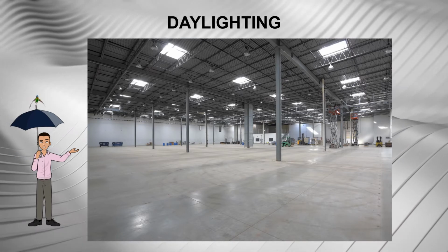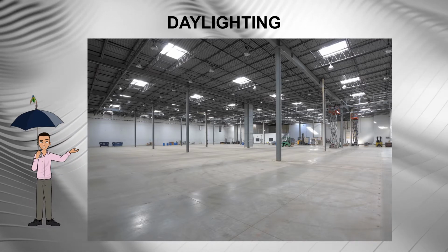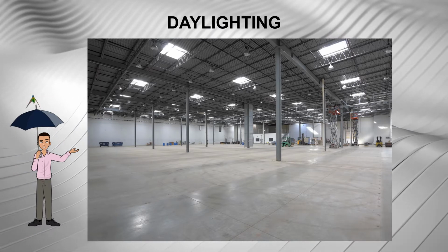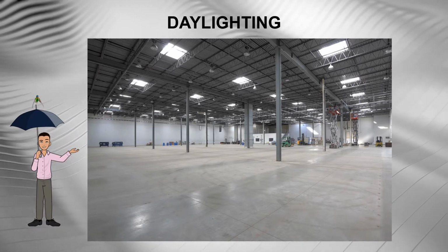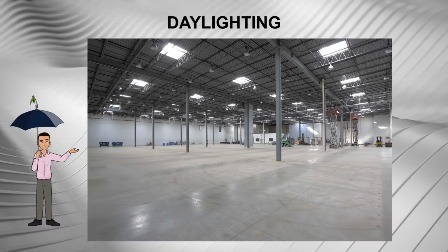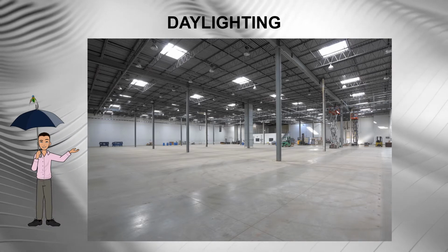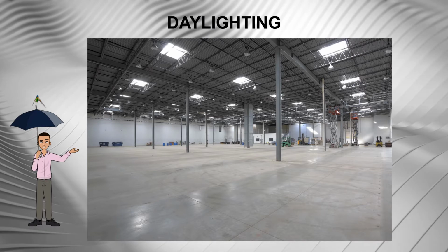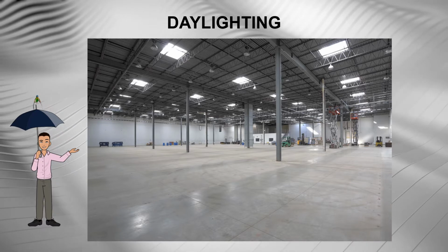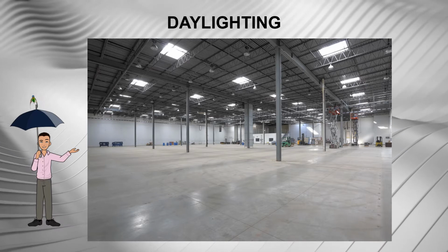Daylighting. Few industries now have particular needs in respect of daylighting, since shift work is often provided for. Sidewall and roof daylighting is usually described as a percentage of the planned area, 5% giving sufficient light for bulk storage, 20% for a working process. Since artificial lighting is usually employed to establish a consistent high level of illumination, daylighting may be provided for visual comfort or for an architectural effect.